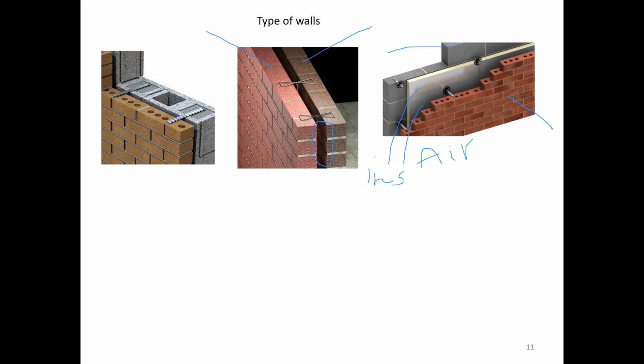So 4. Yes, thermal resistance by conduction, we have 4. And if we add thermal resistance by convection from both sides, then we have 6. Because the air inside and the air outside, then we add also another term from both sides by convection. So we have 2 by convection and 4 by conduction here. Okay.